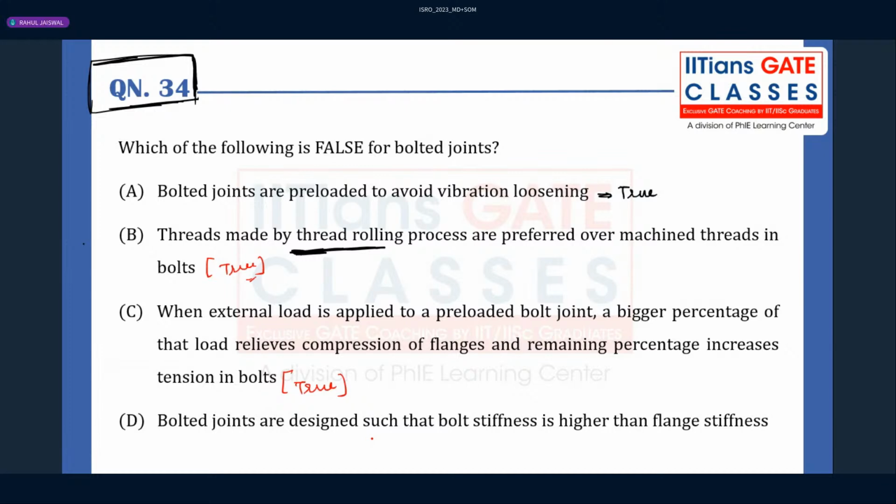So, my dear friends, I told you one statement there. What is the statement I told you? The statement which I have given to you: the bolt materials are generally subjected to CP. The net loads acting on the bolt materials are what? CP. P is what? External load. C is what? Kb divided by Kb plus Km. Kb is what? Stiffness of the bolt.